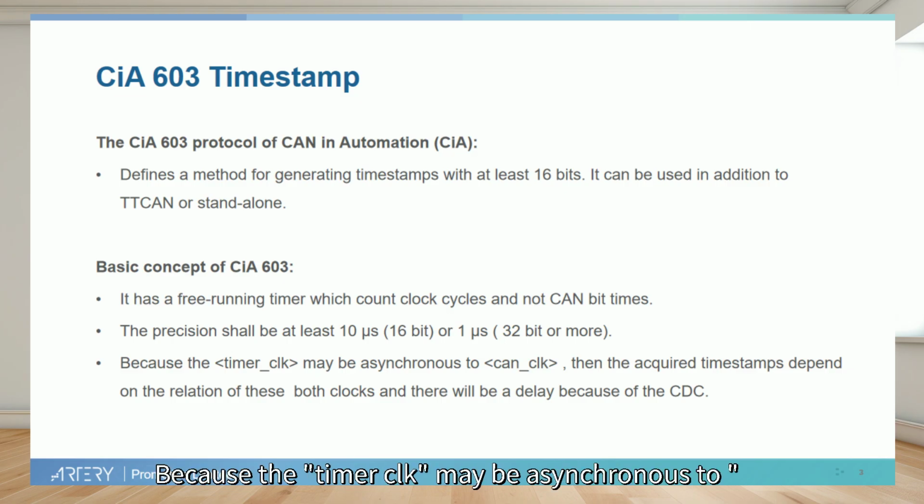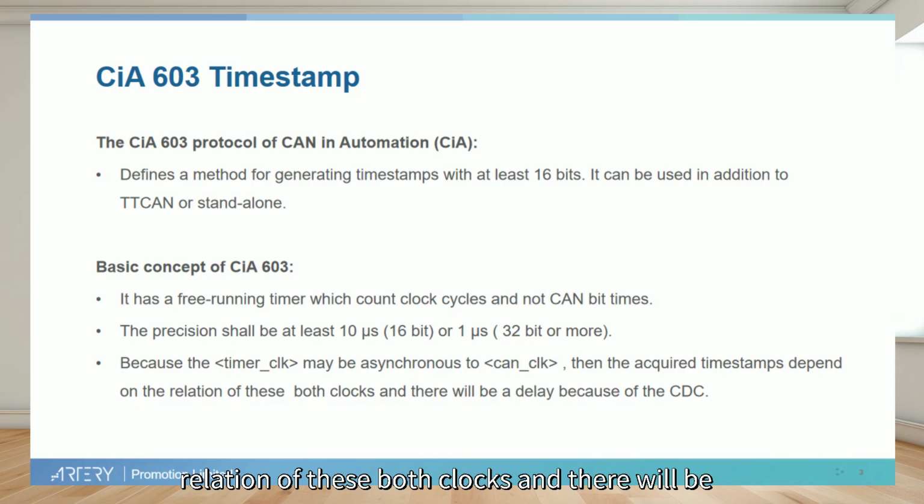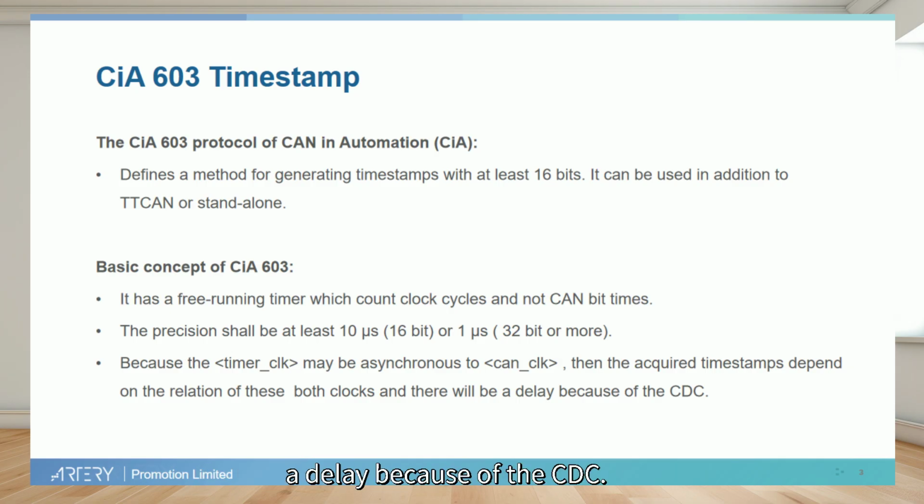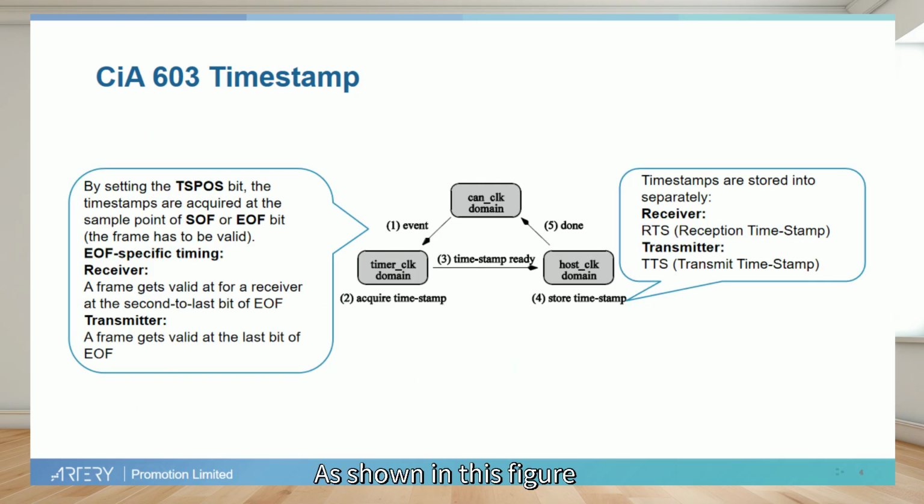Because the timer_CLK may be asynchronous to CAN_CLK, the acquired time stamps depend on the relation of these both clocks, and there will be a delay because of the CDC. As shown in this figure, after an event, a copy of the timer is taken. This is the time stamp. This timestamp is stored into RTS or TTS, respectively, where it can be read by the host. After it is stored, a handshake signal announces the completion of the action.